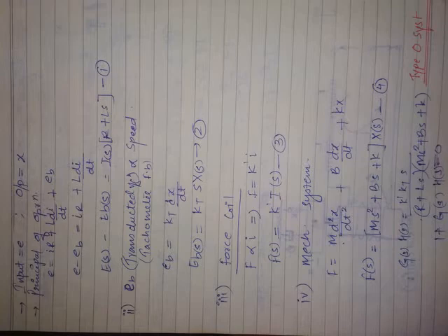From the number of open loop poles at origin you will come to know the type. So this becomes what type system? To find the order, you find C by R and equate the denominator to 0. Or you can construct directly 1 plus GSH is equal to K by S into JS plus F, that is Js square plus Fs plus K. What is the order of the system? So we say that this position control system represents type 1 and order 2 control system.